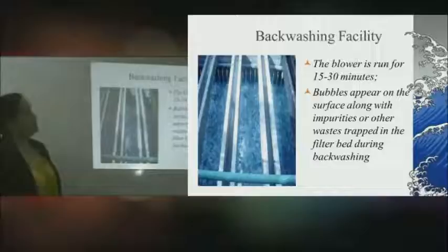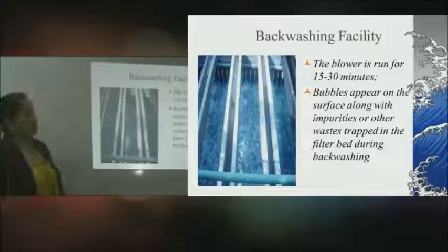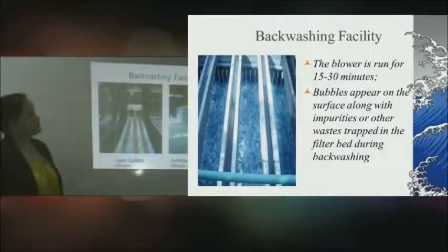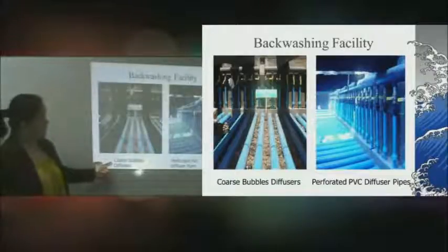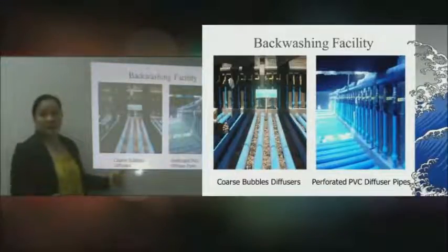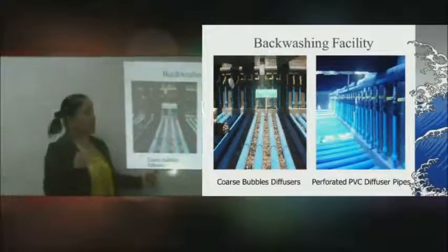Now, this is an example of a backwashing facility being utilized in Putatan during the time of Ayala Land. This is actually made of coarse bubble diffusers so as to give some pressure to clean the filter.